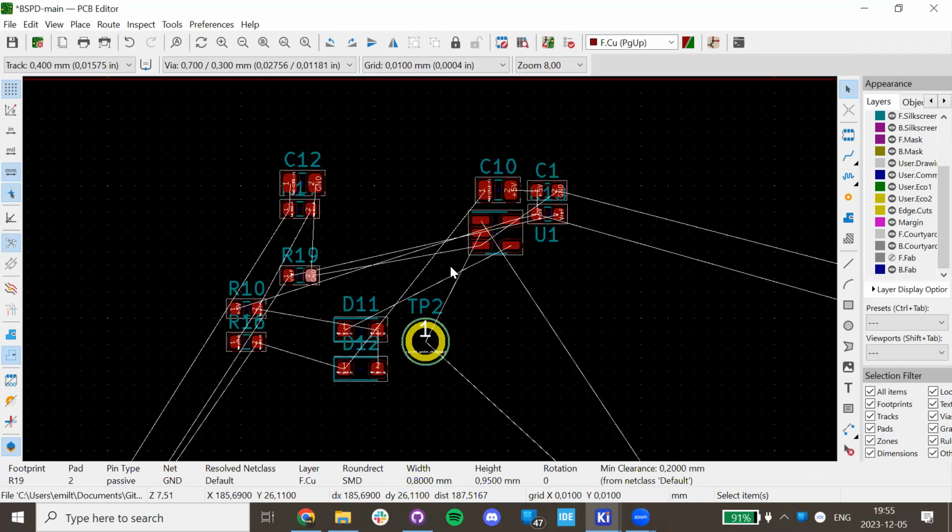And this is a very inaccurate process, I guess, and that's why they can't guarantee tight tolerances, and that's also why you want to have a filled copper layer on all parts, because you want to remove as little copper as possible. Then you can keep your PCB etching time as short as possible, which is good, because otherwise you risk etching away the traces and stuff.